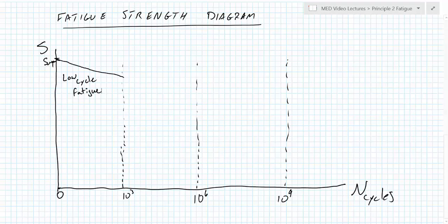So at whatever point it breaks, we can plot that. And so obviously this is a line fit, and statistically we'd have points all around here. But we'll line fit it for the low cycle fatigue. So our equations work okay for low cycle fatigue that we'll be using, but by and large, fracture mechanics will give you a much better estimate of how many cycles something can take if we're talking about it lasting less than 1,000 cycles.